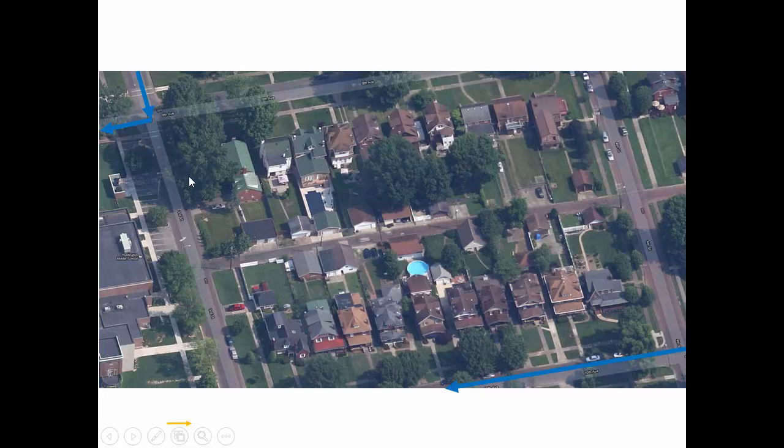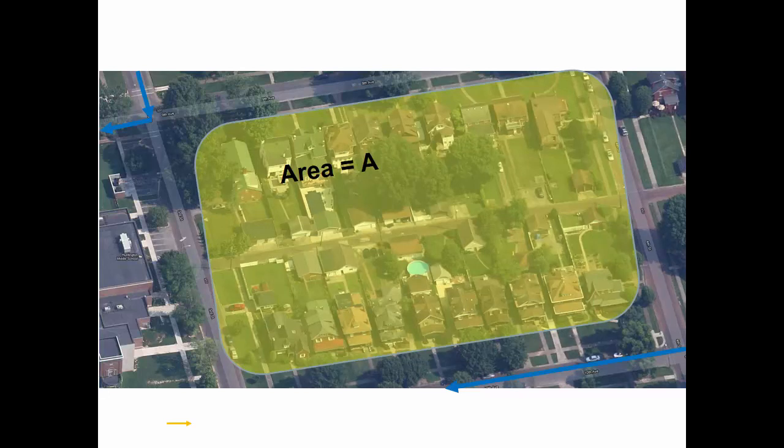But on the other side, you've got this grassy area, these side roads, the roofs, and so you delineate a contributing area. Now I'm using some important technical language that you can find in the handout I gave you, and we'll continue to use through the semester, but delineate means finding the continuous area that's all flowing towards the same outlet. So you delineate a contributing area for a watershed, and the units of that area may be square meters.